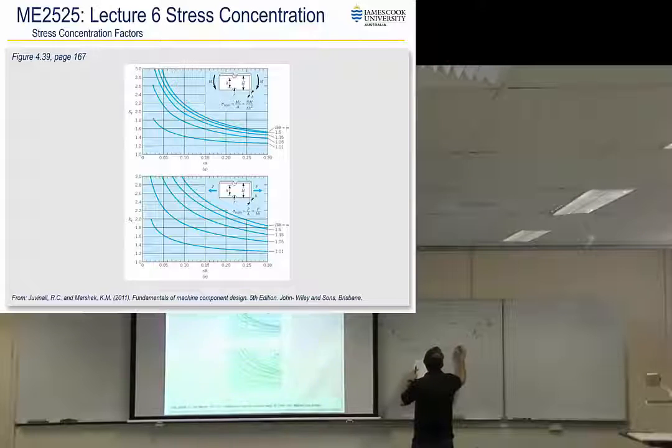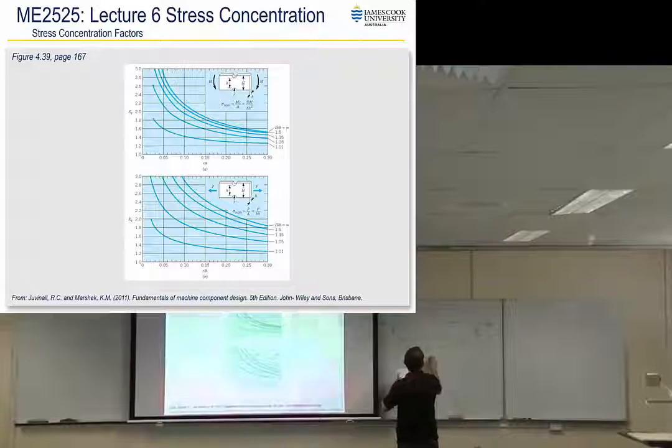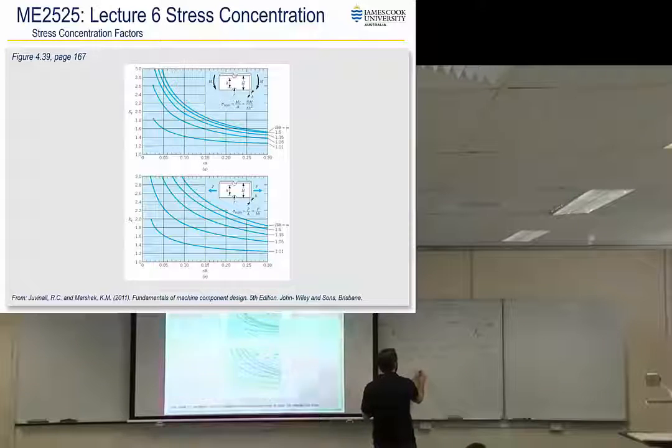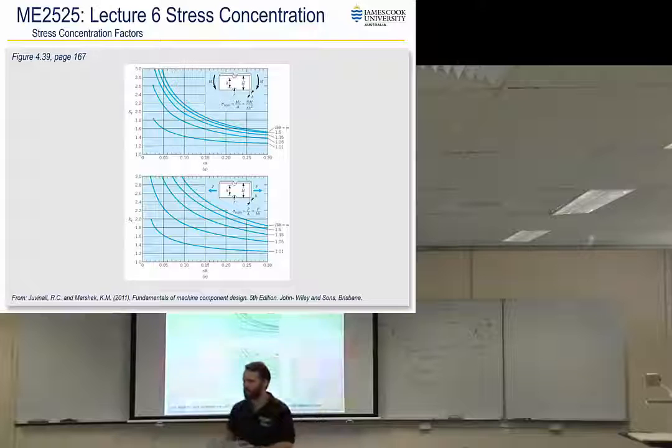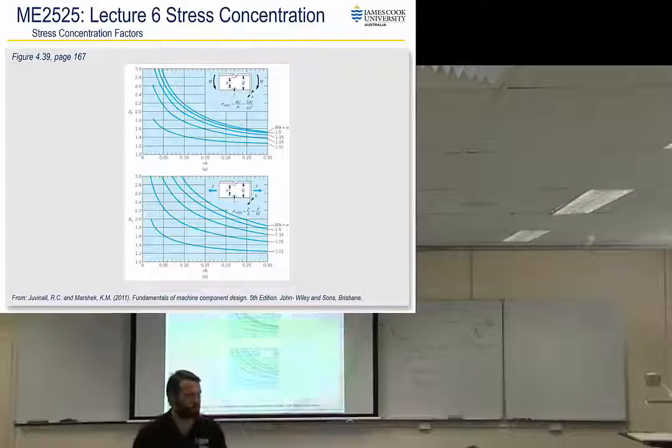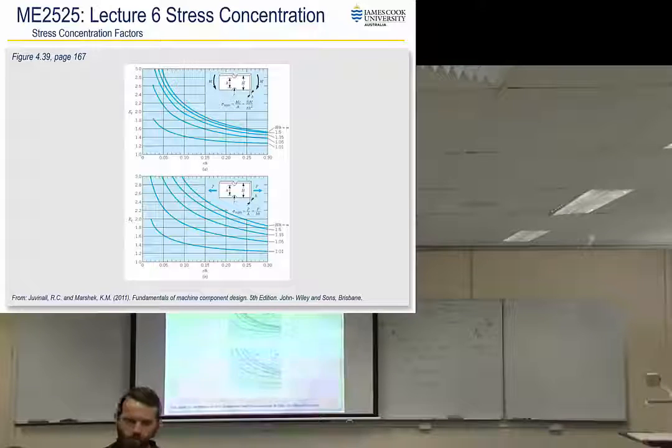for both axial and bending. So you might like to say KT axial and KT bending, like that, such that when you calculate your applied stresses, you can apply the right KT to the right stress to get your properly corrected applied stress element.